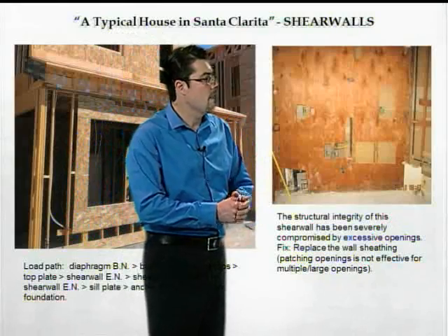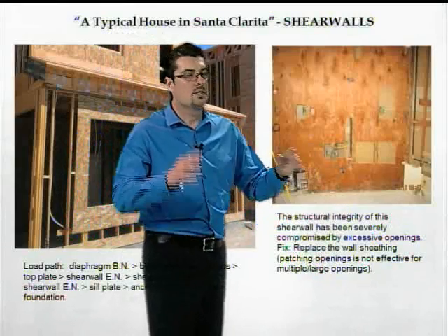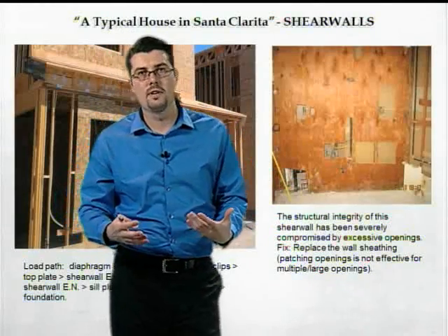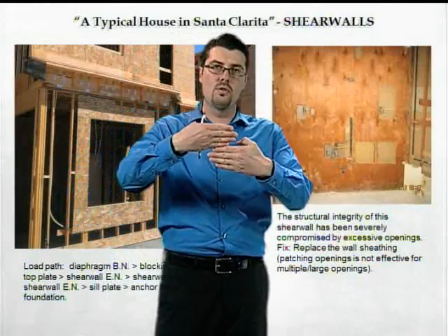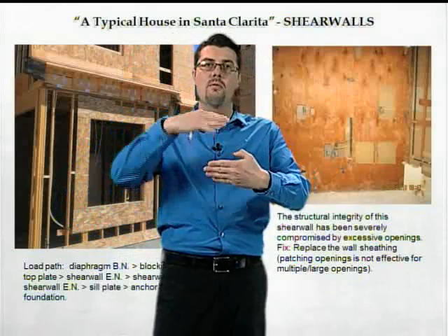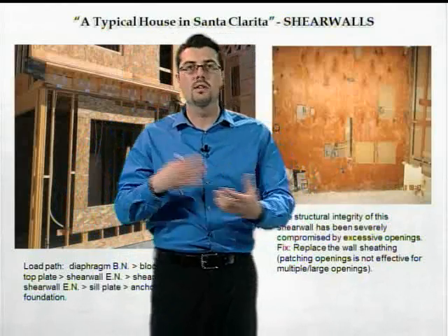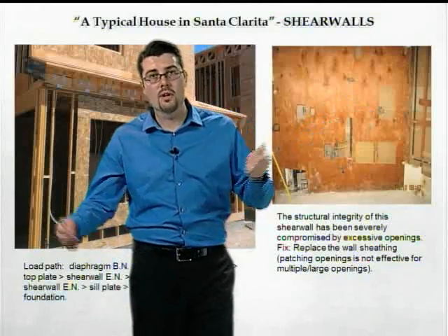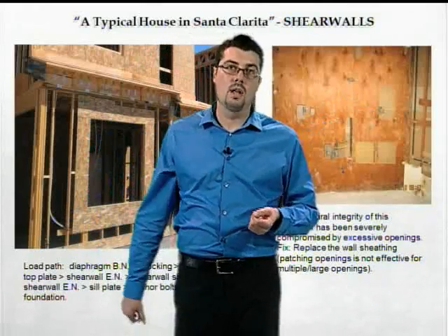Okay. Another thing to keep in mind, simply patching openings in shear walls is usually not an effective fix, because the capacity of a solid piece of plywood versus patchwork, there's a big drop in capacity when you do that. So on a wall like this, you're probably going to look at replacing plywood panels.